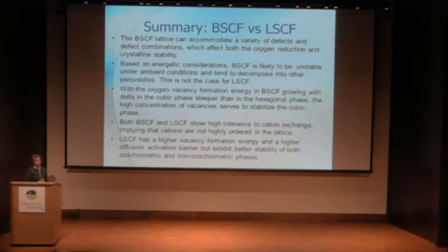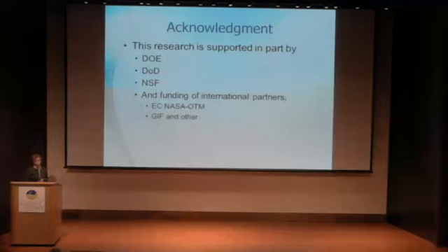Both BSCF and LSCF show high tolerance to cation exchange, implying that cations are not highly ordered in the lattice. They're actually dissolved. Can you hear me still? LSCF has higher vacancy formation energy and higher diffusion activation barrier, but exhibits better stability of both stoichiometric and non-stoichiometric phases. So we think that this is probably a better material for applications.